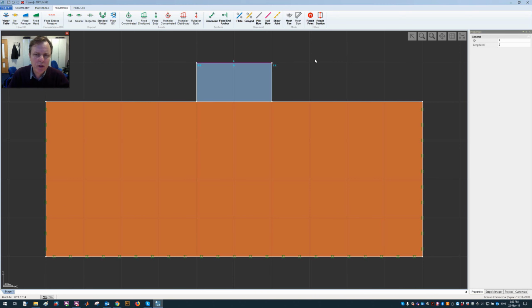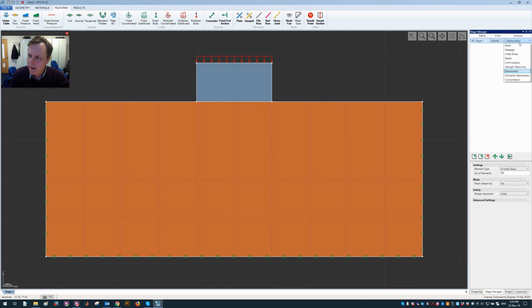The simplest way of doing that is to apply a multiplier distributed load and then run a multiplier elastoplastic analysis. So multiplier elastoplastic analysis is, you could say, a combination of limit analysis and elastoplastic analysis. Elastoplastic analysis in the sense that a sequence of elastoplastic steps are processed, and limit analysis in the sense that you take that to the ultimate limit. All the usual element types, upper, lower, and 6 node, 15 nodes, and the others are all available. So you can actually do sort of lower bound load displacement analysis to failure in this way.